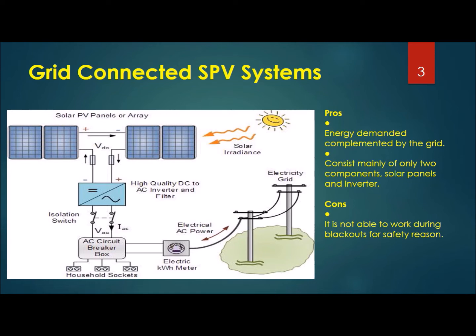The main component in a grid connected photovoltaic system is the inverter. It converts available DC power from the photovoltaic array into usable AC power consistent with voltage and power quality requirements of the grid utility. A bidirectional interface is made between the photovoltaic system AC output terminals and the grid utility network.